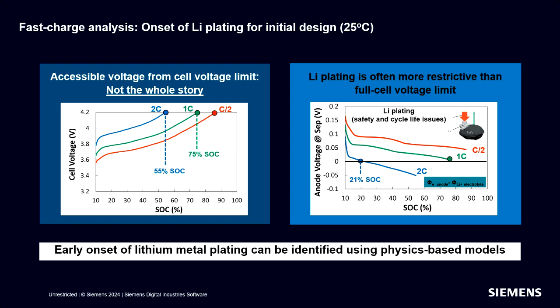On the right, however, we show that this is not the whole story. The lithium plating limit is even more restrictive and is detrimental to safety and cycle life of the cell. If we consider the blue curve, which is the voltage at the anode separator interface, looking at the graph on the right, we can see the SOC reached before this voltage goes negative is 21% of SOC.